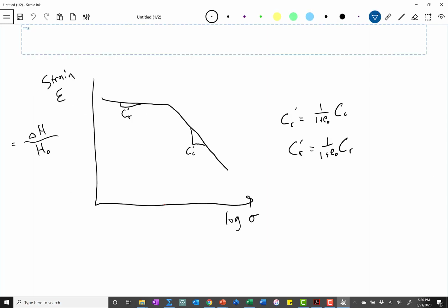We'll load up our consolidation curve. Load it up, load it up. We reach the pre-consolidation stress of the soil, and the slope of that curve will change. And now, every time we increase the stress, that stress becomes the largest stress the soil has ever felt. But until we reach a certain point, if we ever decide to back the stress off, and instead of increasing it, we decrease it, that curve will follow a shape that looks like this. We call that the rebound curve.